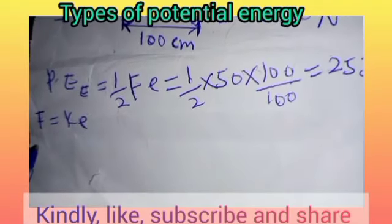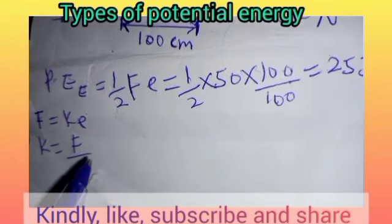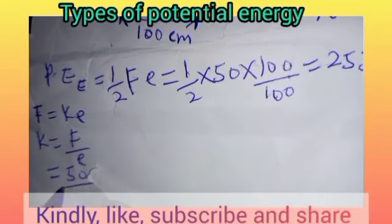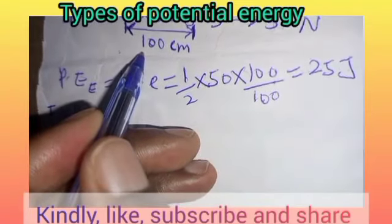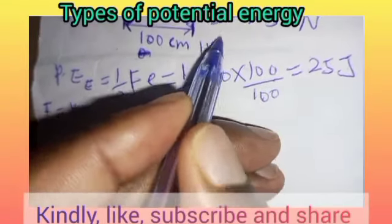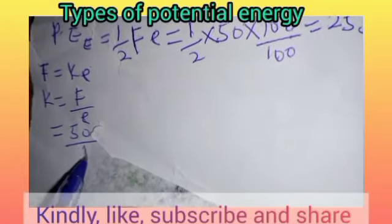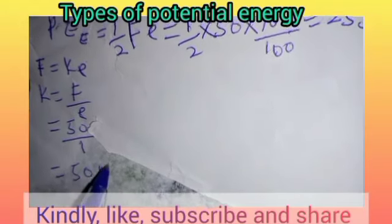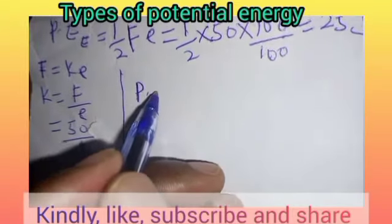So we can obtain the spring constant K is equal to force divided by extension, which is equal to, our force is 50, our extension is 100 centimeters. 100 centimeters is the same as 1 meter. So divided by 1, which is equal to 50 newtons per meter.